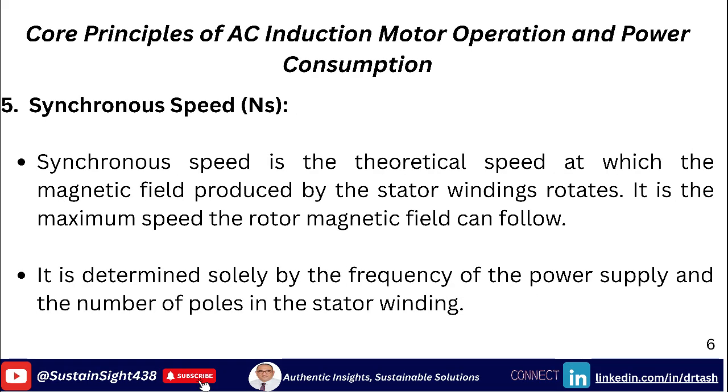Let's shift gears slightly and talk about motor speed. A key concept is synchronous speed, S. This is the theoretical speed at which the magnetic field inside the motor is rotating. It's determined by the design of the motor's windings, specifically the number of motor poles. The stator winding creates magnetic pole pairs. The total number of poles, always an even number, 2, 4, 6, 8, etc., is a fundamental factor in determining speed. More poles mean a slower rotating field for a given frequency.